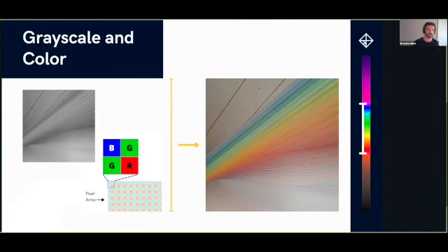You can see on the left here, this is an image I took at the Denver Museum of Art. It's supposed to be wonderful and pretty, but all you get is these alpha values. And that's fine. We're capturing a whole part of the spectrum. This is efficient information gain. It's what you want. But if you wanted more information, and as computer vision scientists we always think more is better, you're going to slap what is called a Bayer pattern on top of that pixel array. You can see that here. The Bayer pattern is BGGR.